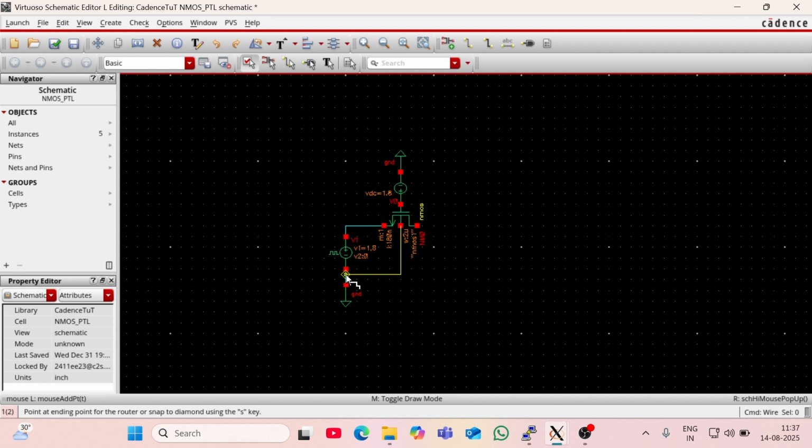The body of NMOS is connected with ground and the body of PMOS is generally connected with DC voltage, because it will reduce the latch-up phenomenon, since a diode is found between the devices which will create direct current. Also the body effect will not occur if you connect this. If the body effect occurs, then VTH can change. For that purpose, I connect the body of NMOS with ground and the body of PMOS with VDD.